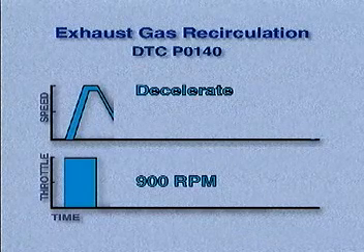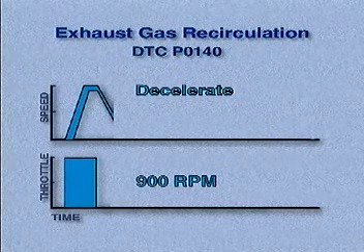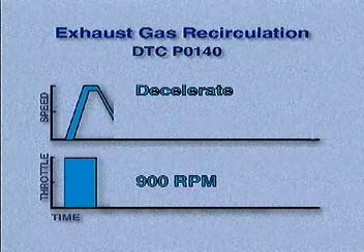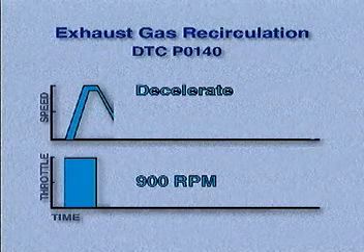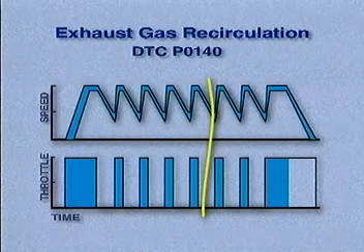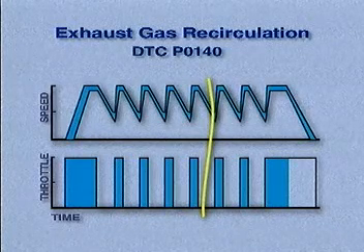Do not apply the brake and do not disengage the clutch on manual transaxle models. During this portion of the test, try not to turn the steering wheel suddenly or turn on the headlamps. Repeat the acceleration and deceleration procedure 8 times or until the readiness test has been completed.